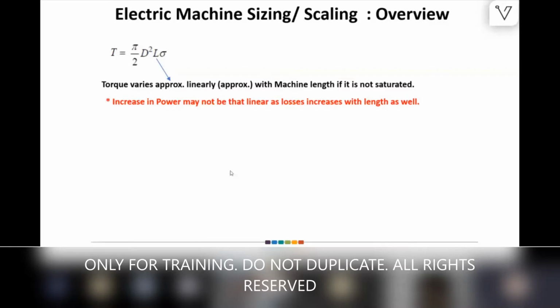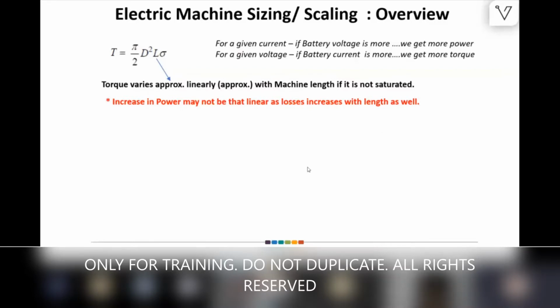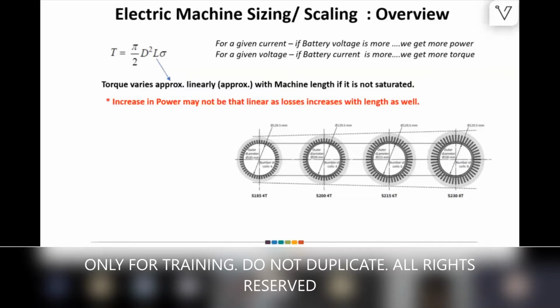When we consider increasing the diameter, there will be tooling cost involved, punching. We have to punch new, different laminations, so the tooling cost and the manufacturing cost go up. But there are situations where you can't help it, because simply increasing length you can't bring modularity. So you have to consider some moderate diameter, where you can downsize and upscale, or degrade it to lower performance vehicles.